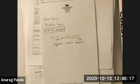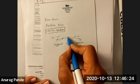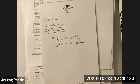So you're looking at the cross-section. As I said, the typical cross-section is about 2% grade on either side from the center line of the road. And that is provided for drainage purposes. And this is what works when the roadway is basically without any curvature.